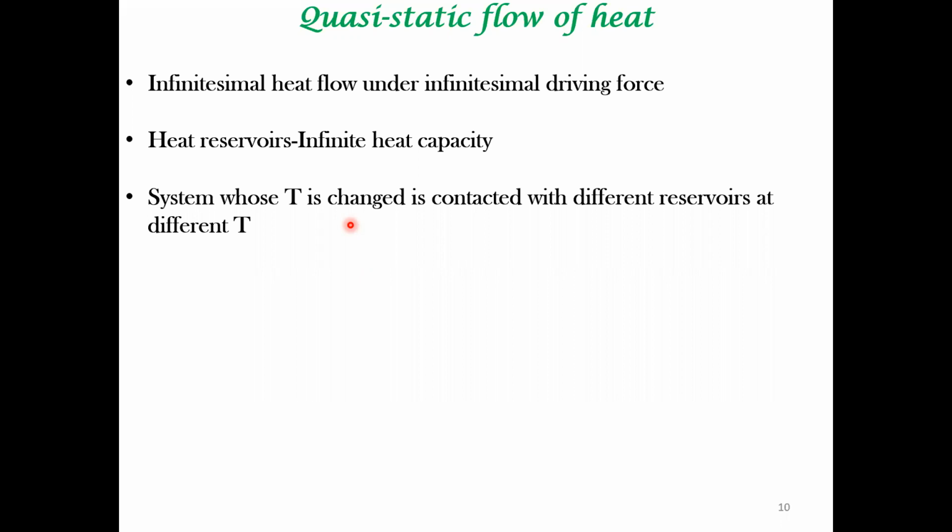You do a thought experiment where different thermal reservoirs at different temperatures are brought in contact with your system. Similarly, when you want to increase the temperature of the system, you bring in heat reservoirs that are at a slightly higher temperature than your system, and then you transfer heat from the reservoir to your system. As the system temperature increases, you envision different thermal reservoirs being brought into contact. This is a thought experiment. It is impractical to envision heat reservoirs at so many different temperatures, but it has certain utility.